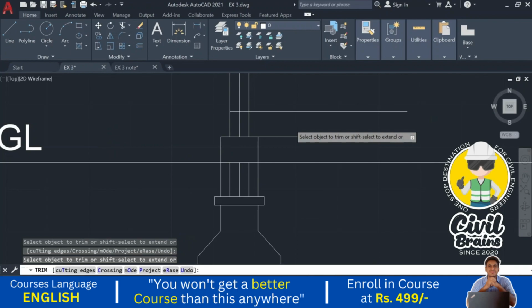Now I take the section here. I draw the section line, and according to that section line we do the section. There is no need to show the section only along one particular line. You can draw a section line randomly anywhere and show the section.